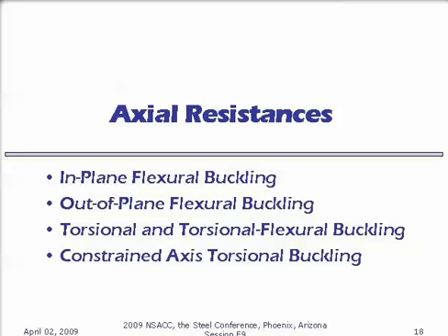One thing to highlight in terms of the gamma sub E calculations, it's really the same fundamental concept that George Lee originally used in their good work, and that was in the previous specifications. But one way to put it is that where in the previous work the elastic buckling solution was tied into looking at the smallest cross-section on a linearly tapered web, we've generalized that.